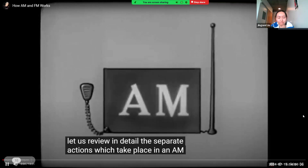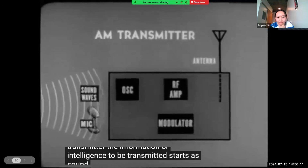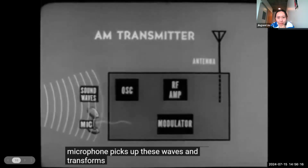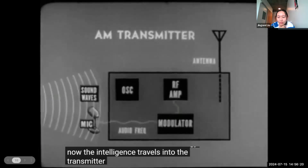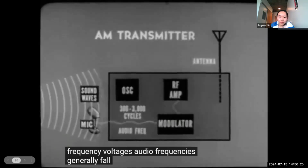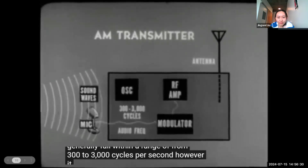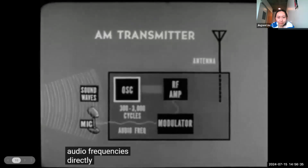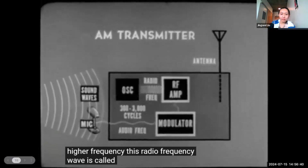Take place in an AM transmitter. The information or intelligence to be transmitted starts as sound waves which travel through air. The microphone picks up these waves and transforms them into electrical energy. Now the intelligence travels into the transmitter, taking the form of audio frequency voltages. Audio frequencies generally fall within a range of from 300 to 3,000 cycles per second. However, it is not practical to transmit these audio frequencies directly. An oscillator provides a much higher frequency. This radio frequency wave is called a carrier.